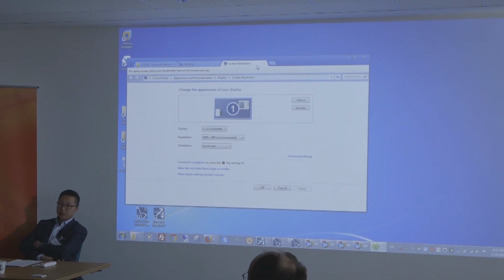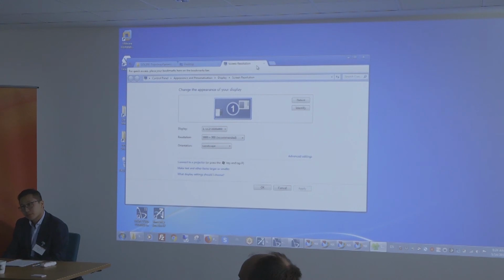If you've got a large model, because again we're using ANSYS, so we're going out of the NX environment into ANSYS, and then solving on a high-performance computer, because it takes several hours to solve, using effectively a separate machine, then you can't use that as a connection, can you? The topology optimization solution uses a SimCenter Nastran solver, right? The output result that you get from ANSYS, you can always import back into SimCenter 3D.